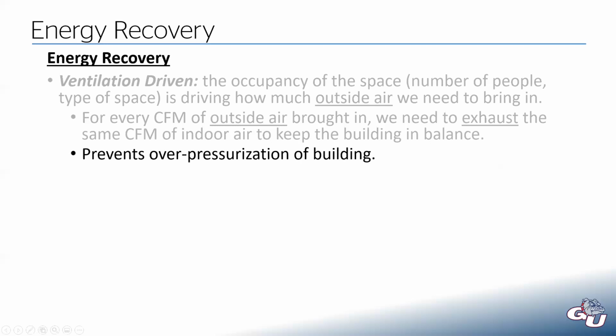Because if we don't do that, we're going to end up over pressurizing the building. And that's when you have issues where you start blowing doors open. Sometimes if you have a pressurized building and a door is closed and pretty tightly sealed up, as soon as you go to open that door, it'll swing open really hard because now you've given this air a path to go, and we don't want that to happen. Or conversely, you don't want to open a door and have it slam you right in the nose. So that would be a ventilation driven system.